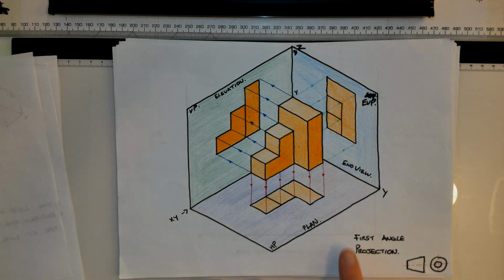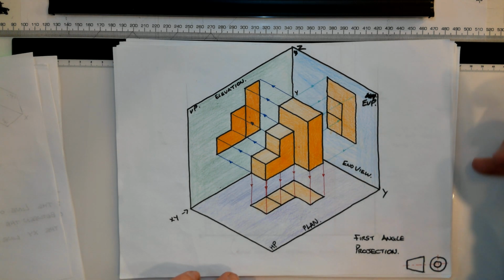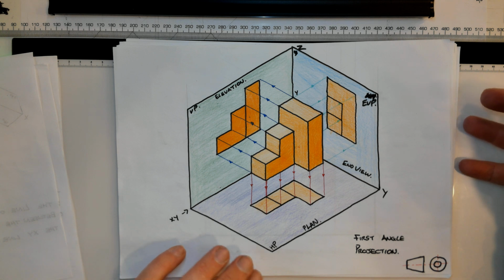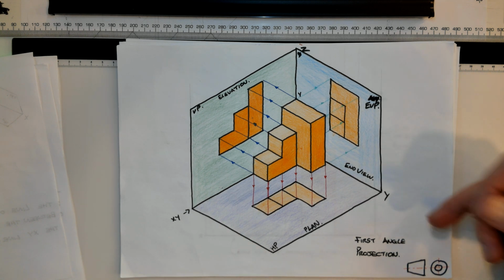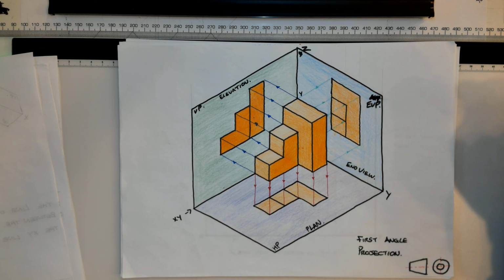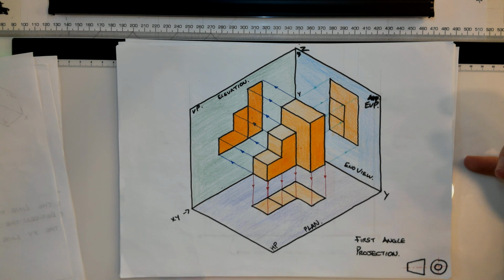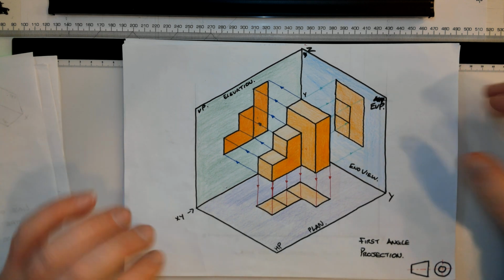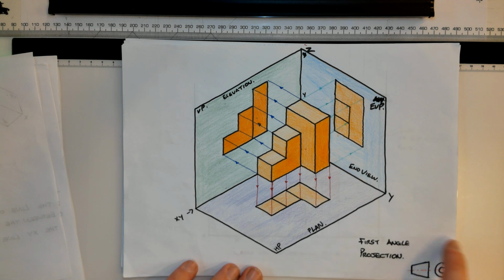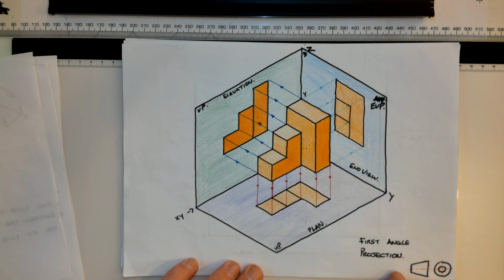Now, this is what's called first angle projection, which is the primary method used over here in Ireland. So we're going to focus primarily on this. We will look at third angle projection in a future video, but for now let's focus on first angle projection. The symbol for first angle projection is here. So imagine this as a conical shape. If we were to stand here looking here, we would see this face, and if we were to stand over here and look this way, we would see this shape.